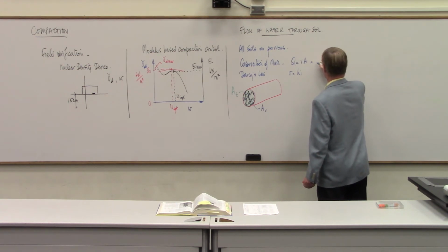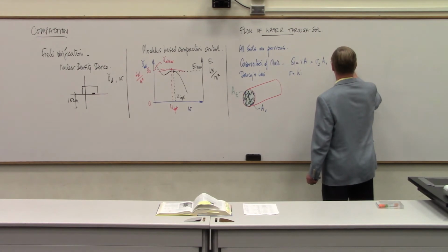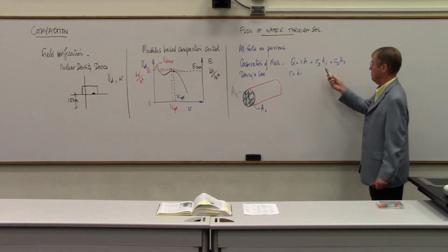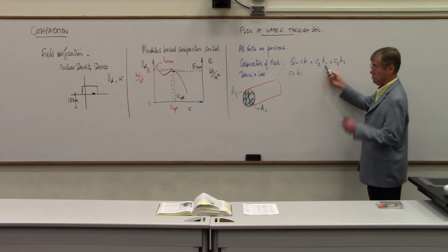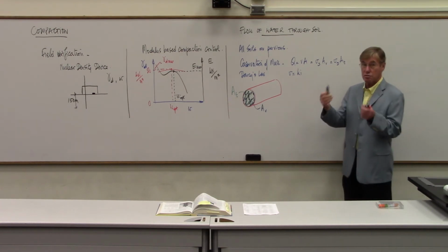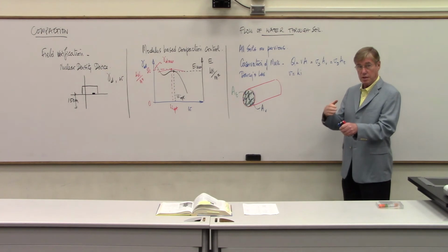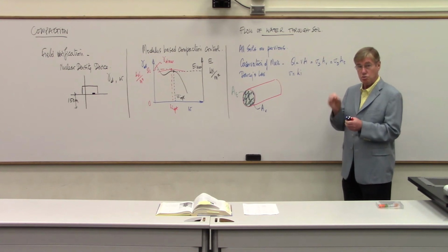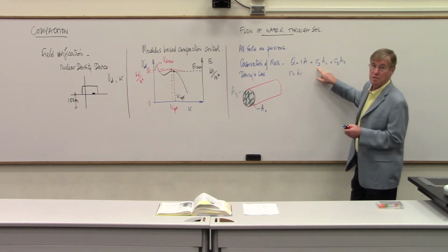So this is going to be equal to V seepage times A voids, or V discharge times A total. V seepage is when you think of the water going through the voids, and that's what truly happens. So if you decide to ride a water molecule and you saw the speed measurements, you would actually see V seepage. So that's the true speed of the water.